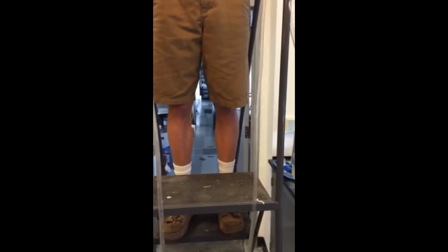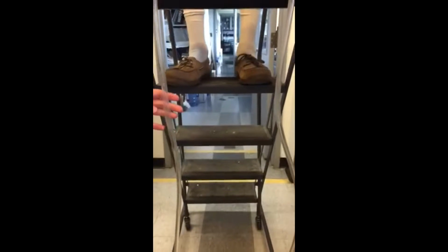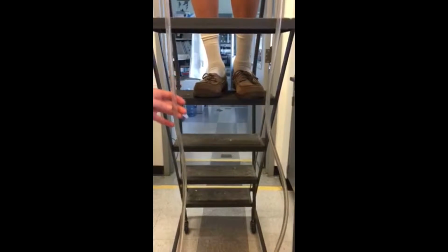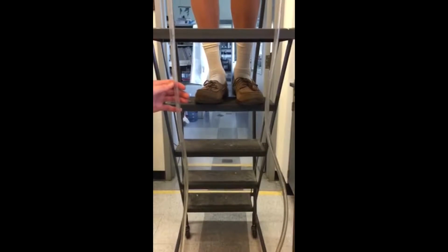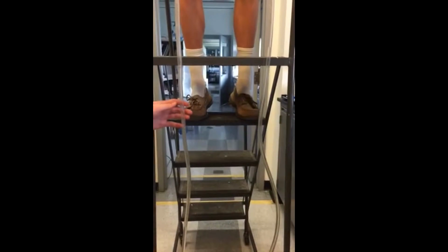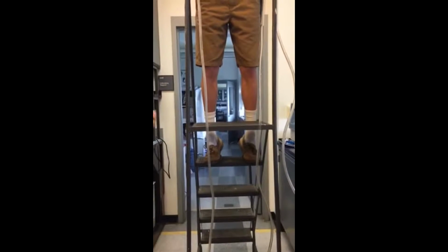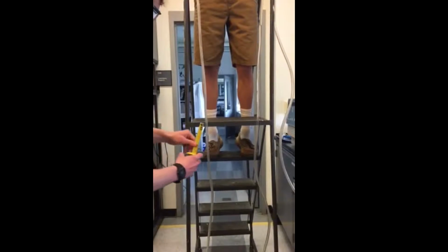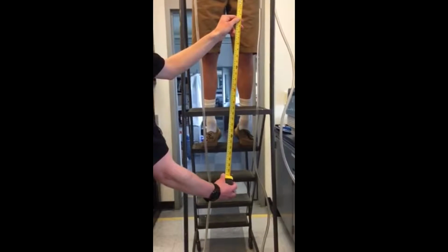Over here, we have the aspirator turned off and fluid in this tube. Because of that, the fluid level is at a constant height because nothing's happening to the system right now. Once you start putting flow through the aspirator and getting suction pressure though, there's going to start to be a difference in the water levels. Remember that pressure can be related to rho g h, so by measuring the difference between these two levels when you have a flow going, you then have the suction pressure for that flow rate.